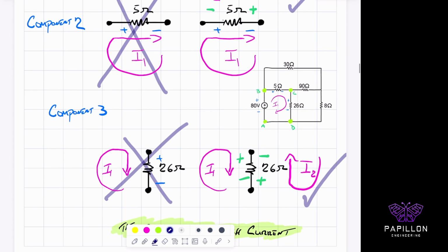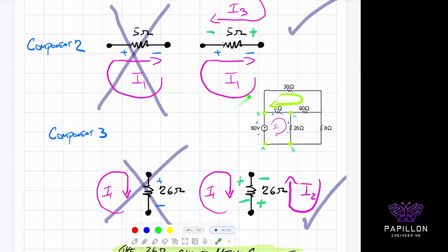Okay, so again, why is that? Let's look at it very slowly and hopefully get the hang of it. As I go around from A, I1 is the same current here on branch AB. AD also has the same current I1, but once we get across branch BC, I1 is definitely going clockwise here, but there's also an opposing current going the opposite way from I3. So let me just draw this out for you so you can see how I3 looks. I3 is going to look like this. It looks like it's going opposed or opposite of I1. And at least we can think about it this way, we can look at it as this scenario right here.